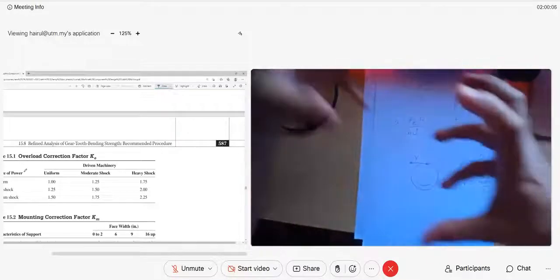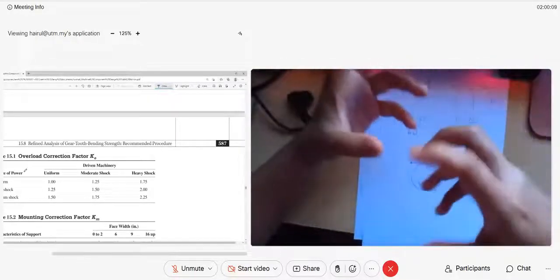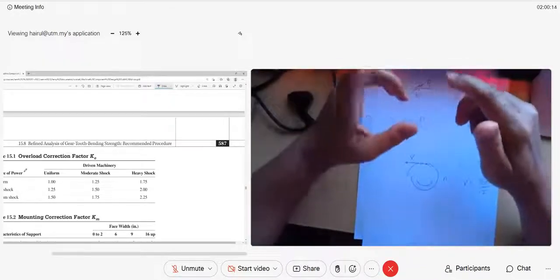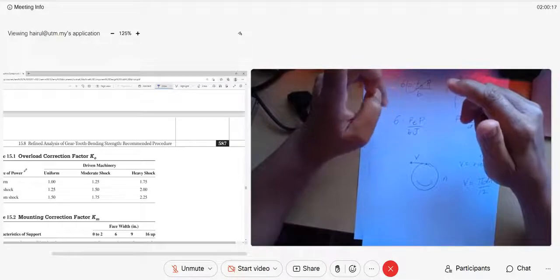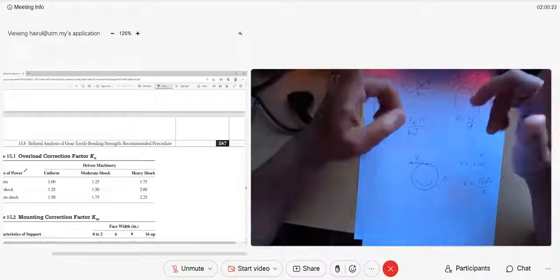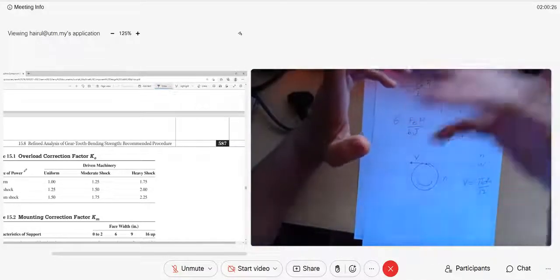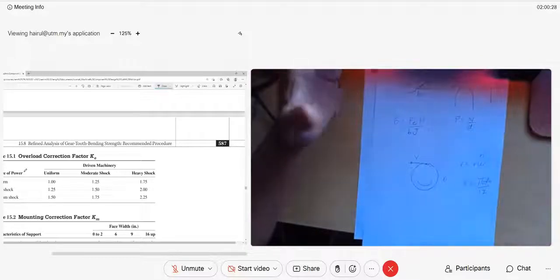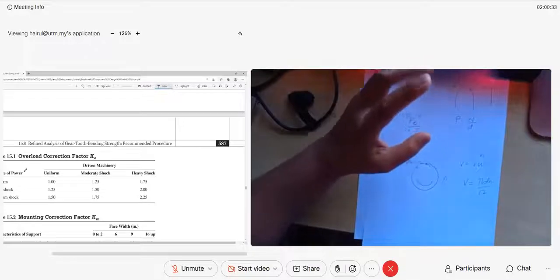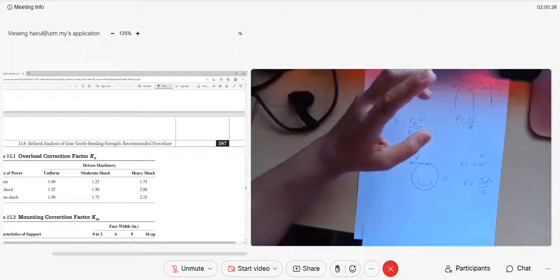In your project, you use a typical electrical motor, like a DC motor. Actually, the source of power is uniform. Unless, for example, I remember we did an example on V-belt, the construction side, they are not using an electrical motor. For heavy duty, 25, 55 horsepower for construction, they need an engine, not an electrical motor. They are driven by fuel, petrol. Engine, that source of power has a little bit of shock, it is not uniform. Electrical motor is normally uniform. This is what we call source of power.